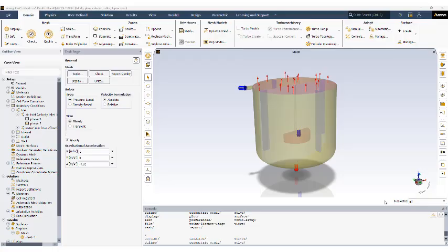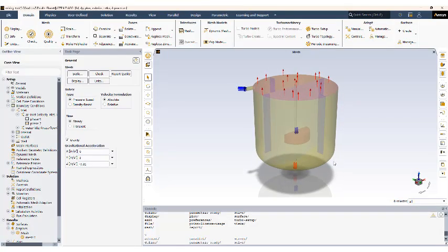Hello and welcome to this short tutorial on how to set up a population balance model in ANSYS Fluent. For this problem I'm using a stirred tank reactor. We are not really implementing any reactions, but we have a two-phase model, basically a multi-phase model using the Eulerian model in ANSYS Fluent. To give a brief overview, this is our geometry, which was adapted from the ANSYS Fluent